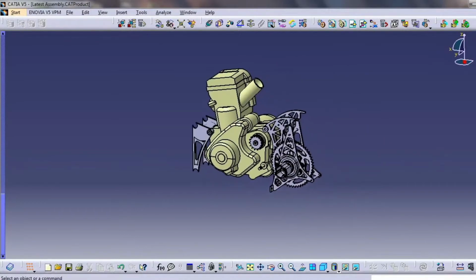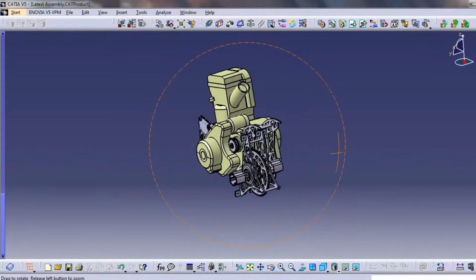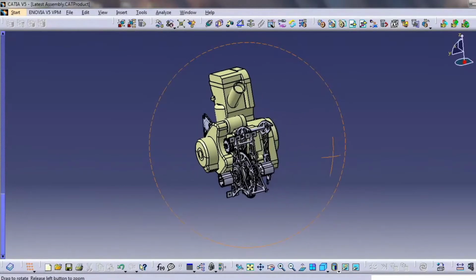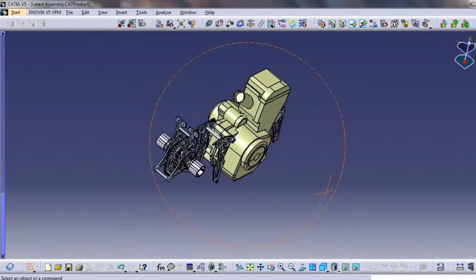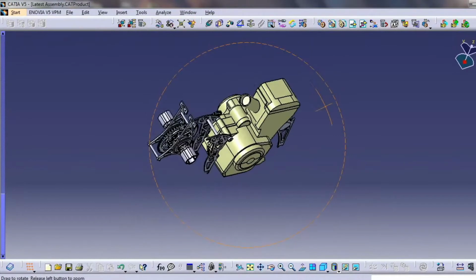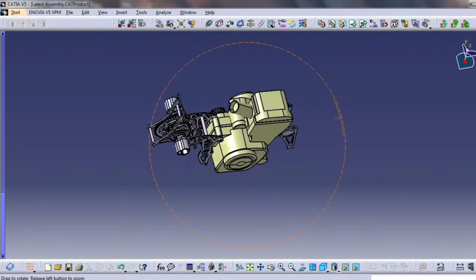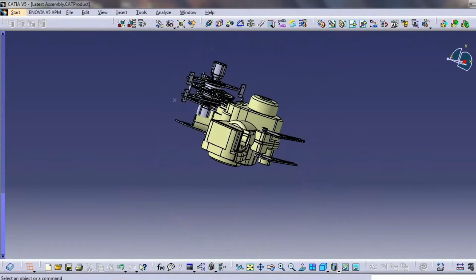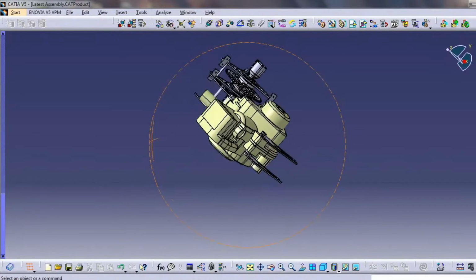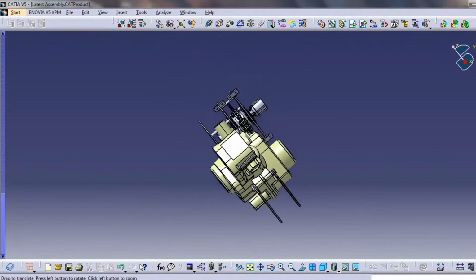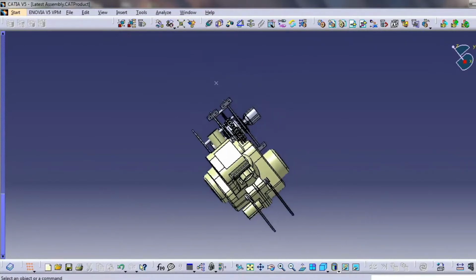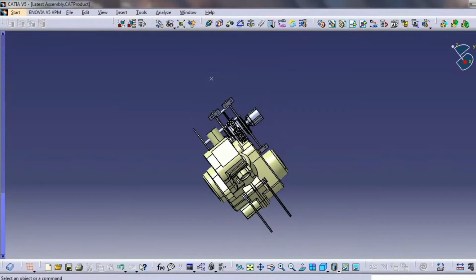So we come to the designing part. While designing the drivetrain, we took various iterations of at which gear what is the RPM that we receive from the engine. By using these iterations, we decided the reduction ratio to find out the maximum acceleration and velocity. So what is reduction ratio? Reduction ratio is nothing but number of teeth of large gear upon number of teeth of small gear. This ratio is called the reduction ratio.